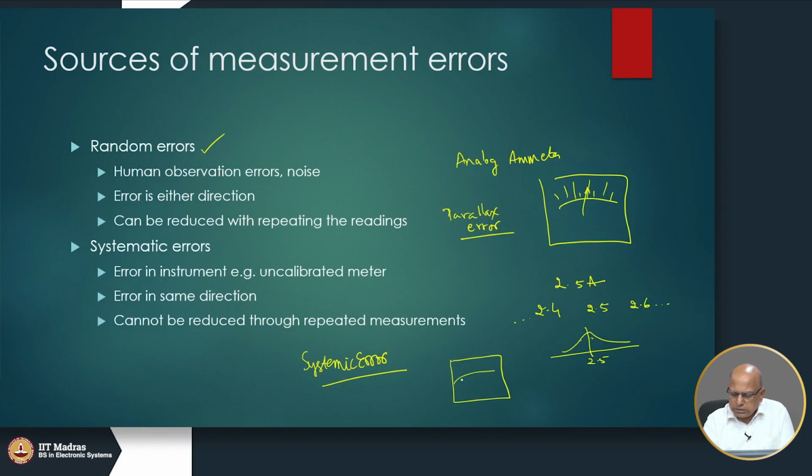If you happen to know that there is a 1 ampere current in a particular circuit, you put the ammeter in that and make sure that it is showing 1 ampere. So, you take a known value of current, measure it using the ammeter and make sure that it is reading 1. Then you have calibrated.